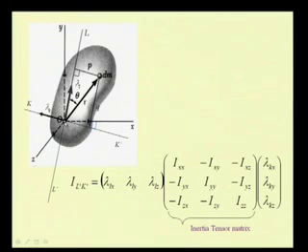So, now that we have the expressions for the product of inertia as well as the second moment of inertia with respect to an arbitrary axis, it is possible to find the inertia tensor associated with an arbitrary orthogonal axis system which is rotated with respect to O. So, now I can define another vector, say z prime.